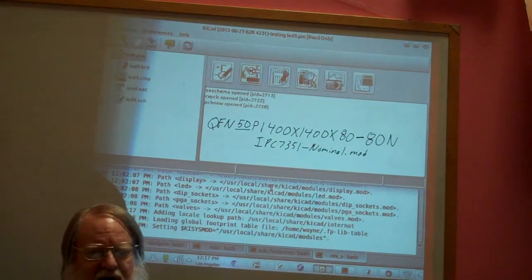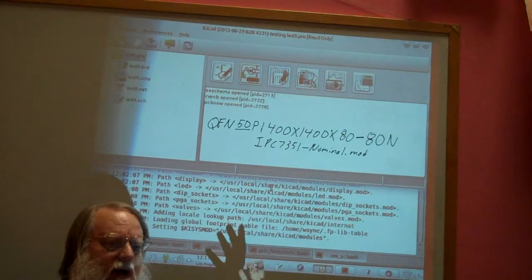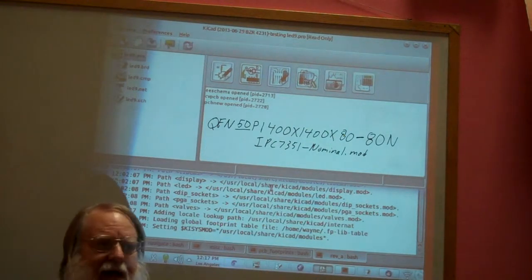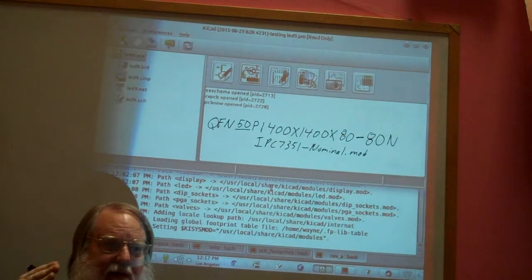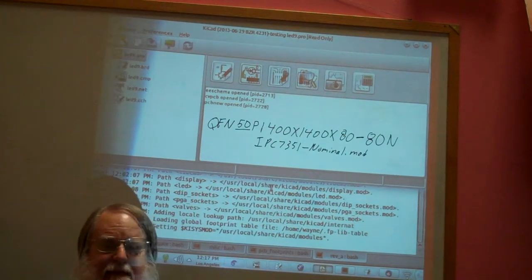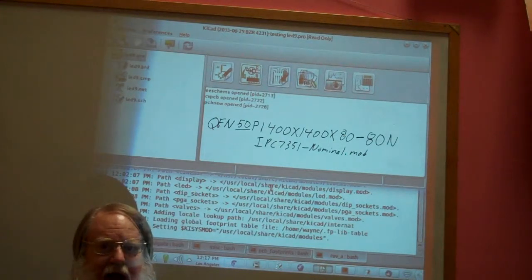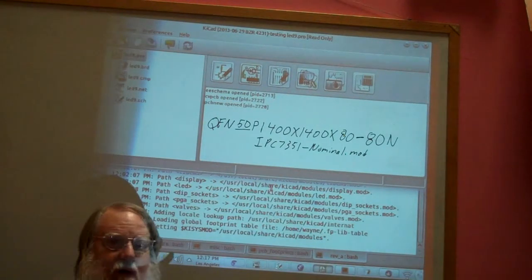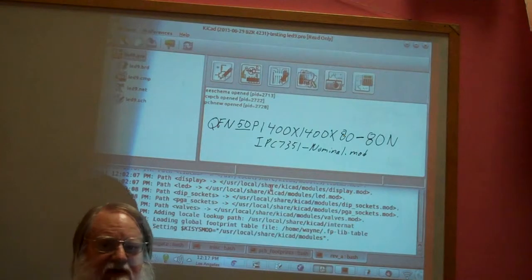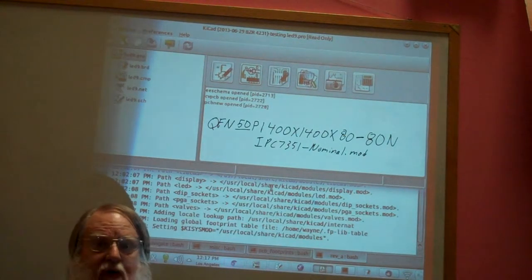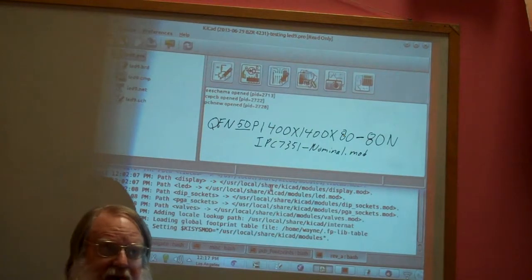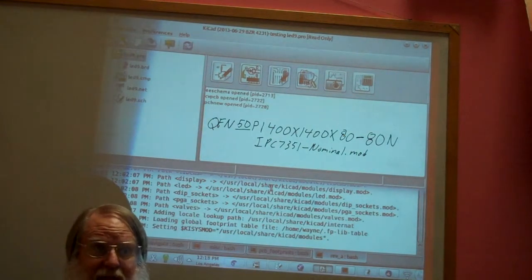And that's the final thing, let's say final, but when it comes to footprints, almost everybody keeps track of their own library that has their own good stuff that they know works. Okay, everybody for all packages across the industry seems to do that. There may be people who are sufficiently happy with the quality control with some of the high-end ones like Altium that they don't keep their own libraries. But basically, you need to be very worried about it.